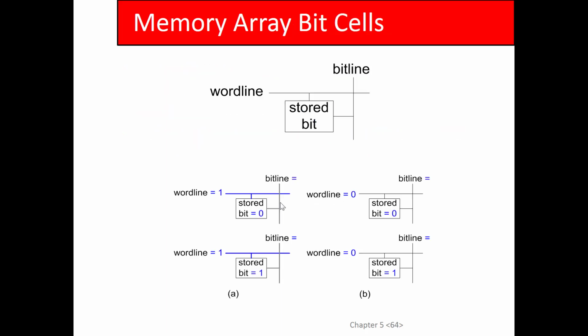Let's see. All right. So internally, there's this terminology that I think is applied even to flash memory. It's a common terminology. You have this bit line, where the bit line is generally associated with the columns, right? And then there's the word line that selects one of the rows. This is the easiest way to think about it. So the bit lines are shown here as this vertical line. The bit line is what comes out, like if you read the memory or write to the memory, the bit line is the data that comes out if you're reading or goes in if you're writing.